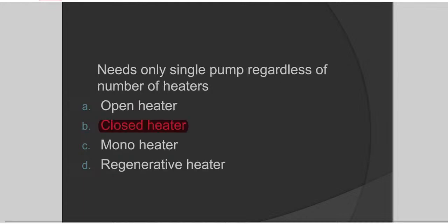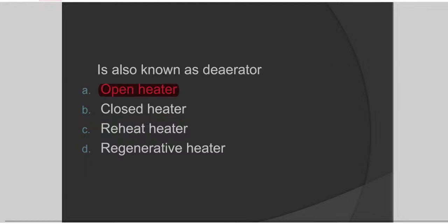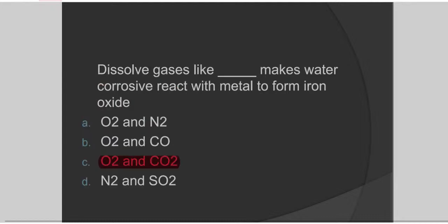____ needs only a single pump regardless of the number of heaters. A. Open heater B. Closed heater C. Mono heater. Regenerative heater is also known as deaerator. A. Open heater B. Closed heater C. Reheat heater. Regenerative heater. Dissolved gases like ____ make water corrosive and react with metal to form iron oxide.